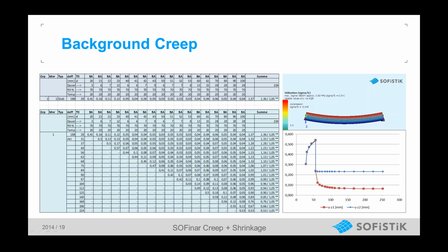What I did in the next slide, which you should now see, is simply make a copy of the creep values from the report browser output. In the top table, you see we are following the standard creep effect. In this case, I applied lots of creep stages just to split it up in more detail for a nice little plot with an Excel sheet. For this beam element, we have a final creep value of 1.37, and that's it.